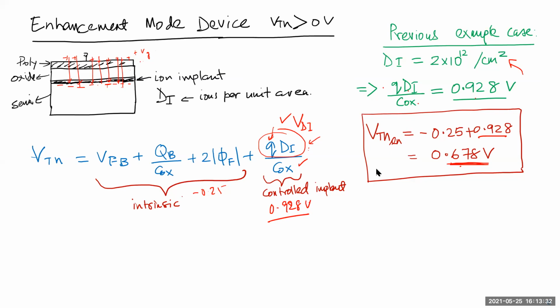So when you take two materials and connect them, you saw the bands bend, right? Because you have two materials of two different Fermi potential. But thermodynamics says that the Fermi energy level should be the same for a material which is in steady state, with steady state in the sense that there's no electric field or magnetic field imposed on it. But if that's the case, then the conduction and the valence band have to bend. So this potential is to actually flatten that band and bend the Fermi potential. Okay, so take it from steady state to a non-steady state.